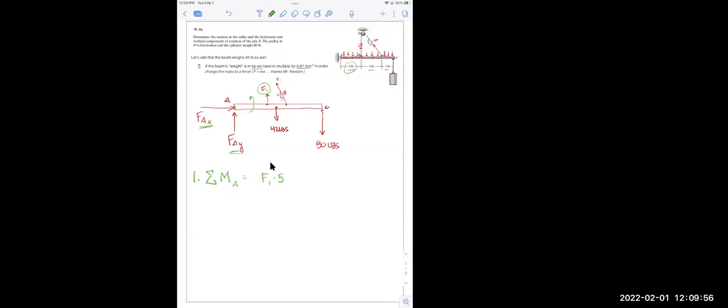That's cool. But then I have another force one. And it's also trying to get it to rotate counterclockwise. But again, do you understand? I don't want to leave that force one alone, because if I do, then the distance I need is perpendicular to that. So it's like I'd have to figure out what that yellow distance is. That's really hard. What I'd rather do instead is convert it, as we've been talking about, to its XY components.